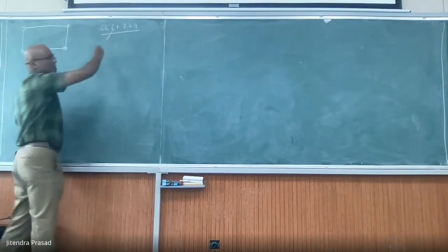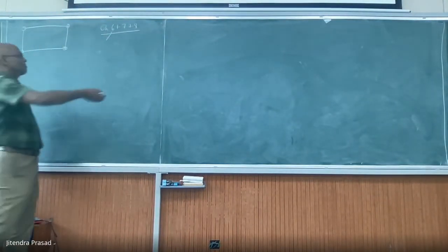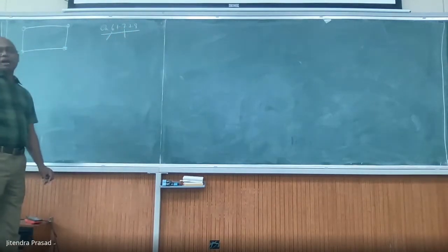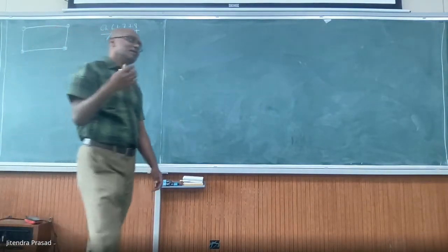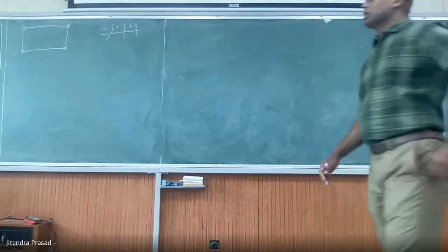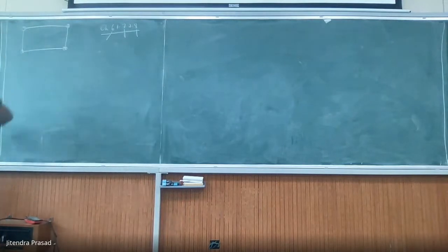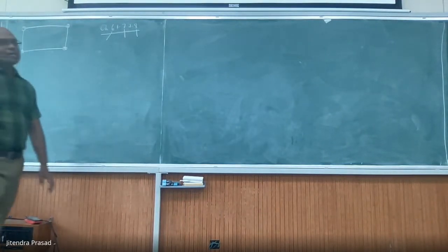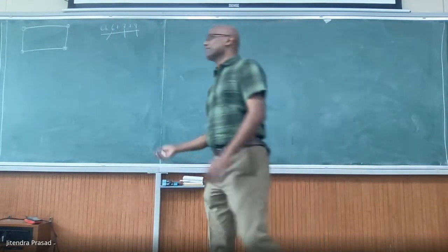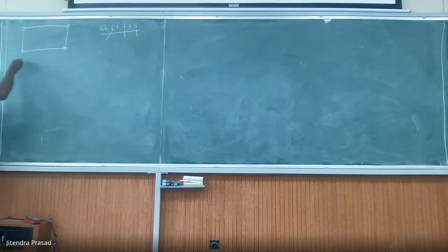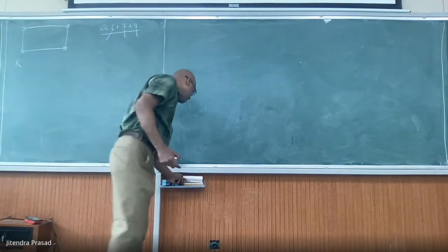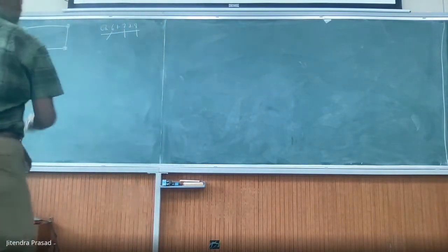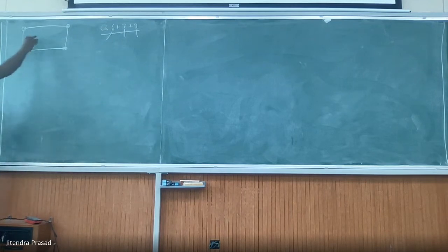Chapter 6 is all about the weak formulation, from a strong form to weak form. This is about the types of elements, how you formulate the test functions, and how you solve it. Now we have done this already for the triangular element. So now we are moving to four noded elements, and it's easy only. The main thing in this case is how to find out the stiffness matrix. All the others you will use the same method. Whatever we have done for triangular, we will just repeat it for the rectangular element.